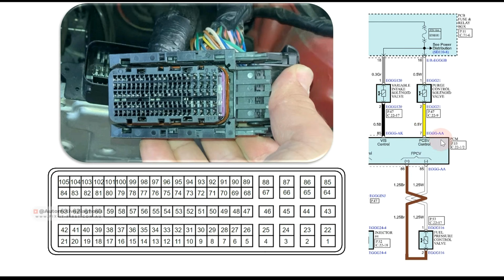So it means you just need to look up this connector code in the wiring diagram, because wiring diagrams normally include the connector details as well. And after finding this one, you can identify the pin numbers. So this is exactly this connector. You see some bigger pins over here, some bigger pins over there. On this side we have some bigger pins, just a little bigger than the other ones, not too big. And you can identify the pins by looking at this.